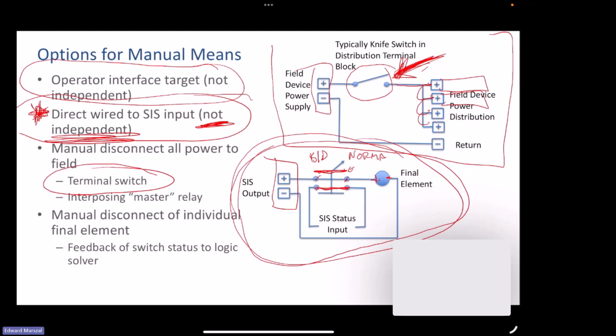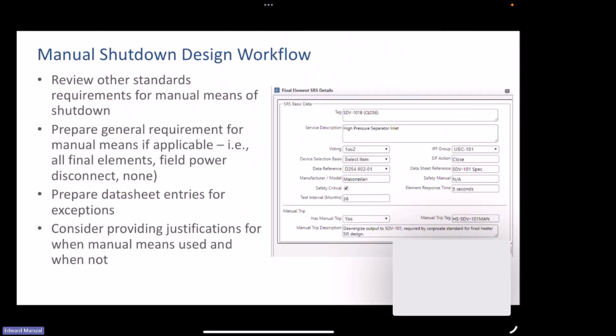But then again, if you were cheap enough to buy that $99 PLC from PLC Direct, you're probably also going to want to be so cheap that you're just going to want to put a $1 knife switch in your terminal strip so that if everything's gone awry, if that toilet overflowed, you're going to send somebody into the marshaling room to flip that one switch and just go ahead and disconnect all the power that's going out to the field. Okay, so that's all the technical content.